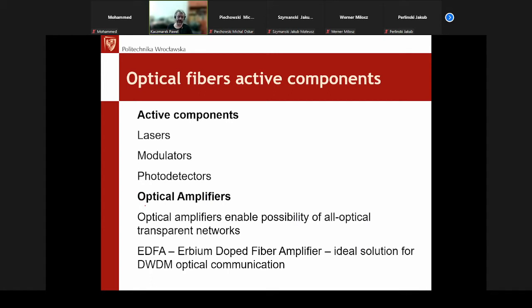They appear mostly in telecommunication, but using these optical fiber amplifiers we can also build, for example, fiber lasers. For certain applications, fiber lasers have quite high advantages over classical lasers. So you can use active fiber as a gain medium to create a laser. In the lab you are also measuring such a laser. This Q-switched, I mean pulsed, fiber laser is made of an erbium doped fiber amplifier.